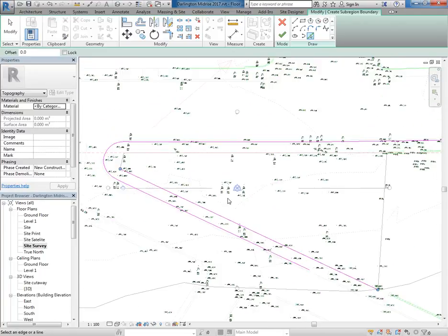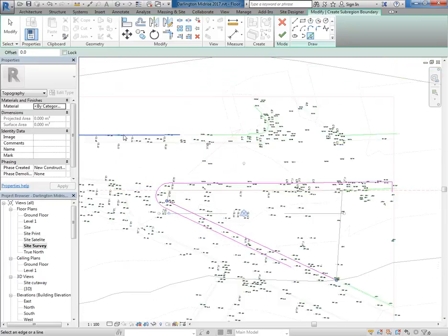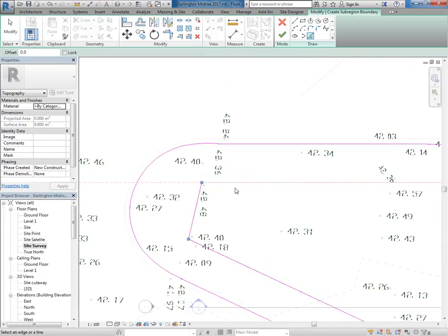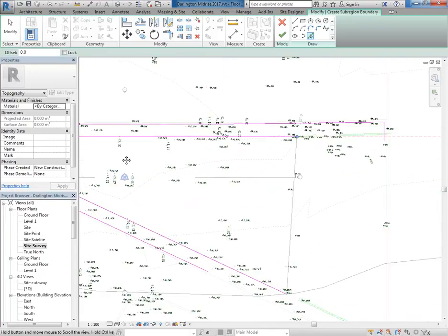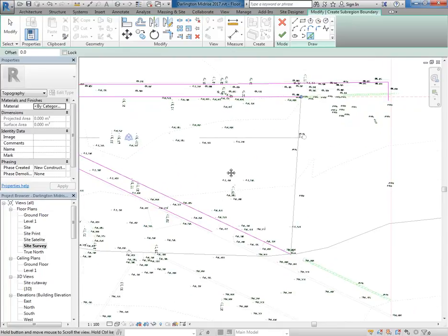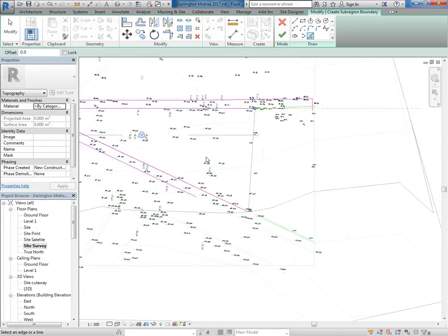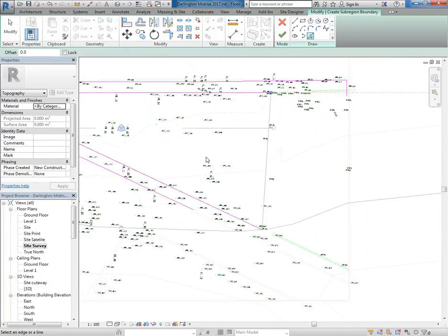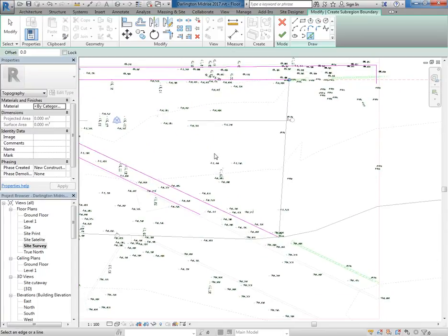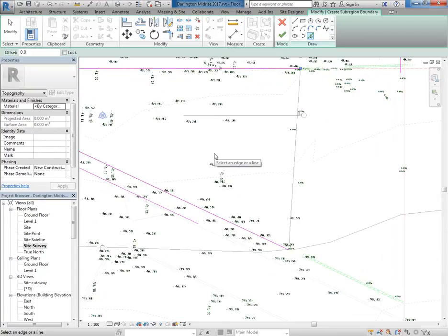And so then, later we can apply the same principle when we work on the road, because the road will come next, it'll go next to the footpath, and I'm going to have a lot of subregions that are right up next to each other. And just having the AutoCAD lines there will make everything much, much easier. But we did the boundary line using the DWG line anyway. So even if we didn't do that, we could still pick it off there anyway.